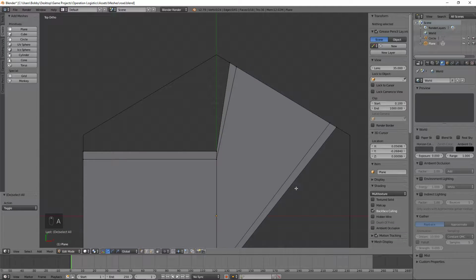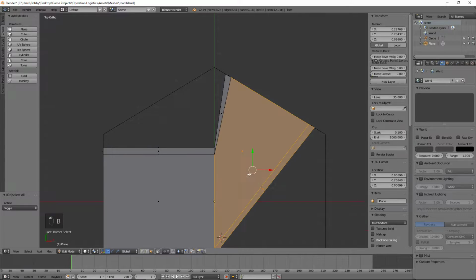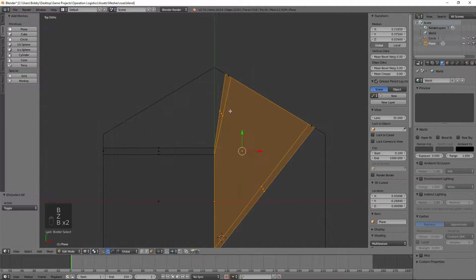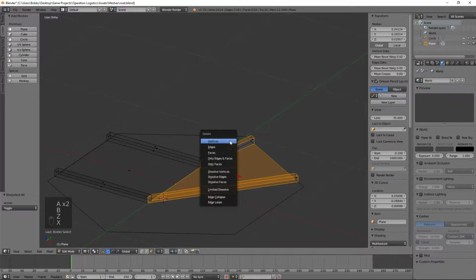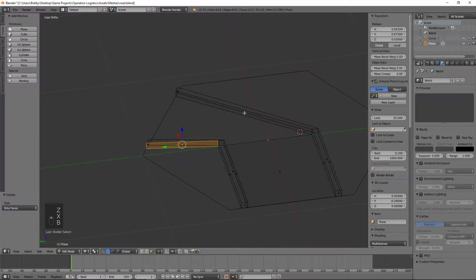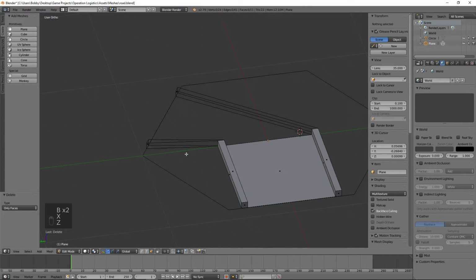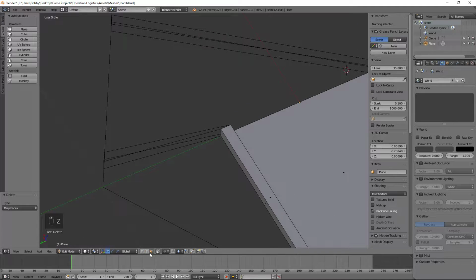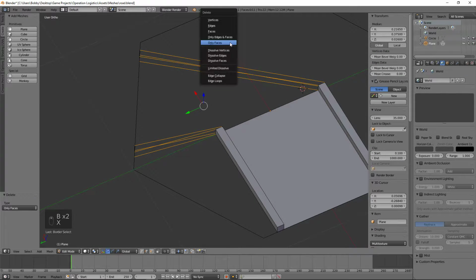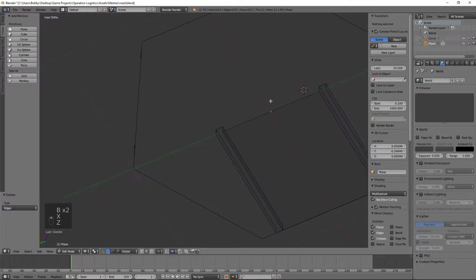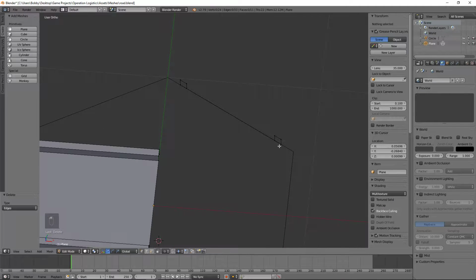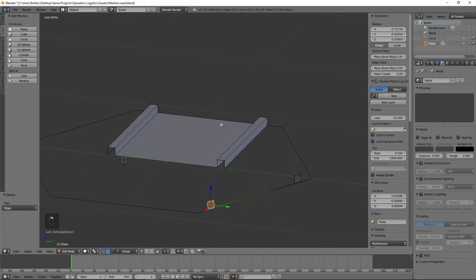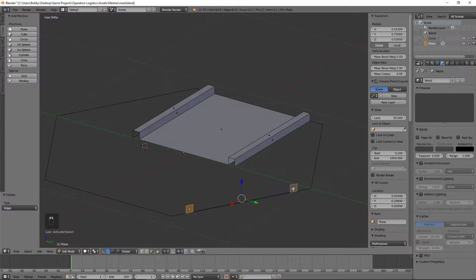So the next thing that I want to do is I think we should go ahead and get rid of only faces out this direction. So let's get rid of only faces out here, as well as these faces. Delete only faces. Okay. I'm going to go into edge select mode, and I'm going to go ahead and delete these edges as well. But I want to have these vertices still over here. And then these can still be faces, that's perfectly fine.